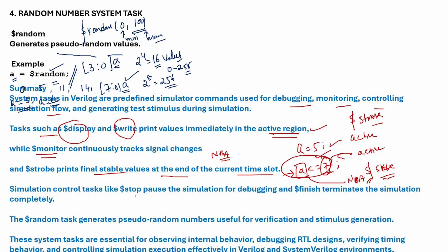And $stop, as I told you, just pauses the simulation, just suspends it, and then you can resume the simulation again. And $finish completely terminates the simulation. There is no mercy here.